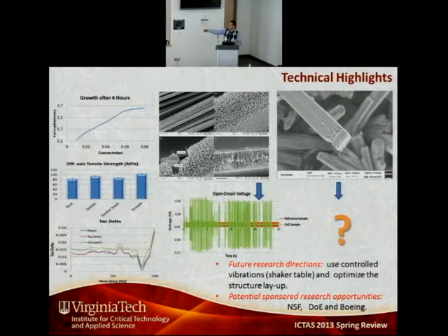So here in the red is the reference sample, where we see that there is no piezoelectric effect or energy harvesting. The green one is the sample with zinc oxide. So we see here that the voltage reached about 0.1 volt. This is an open circuit. So this basically shows us that there is energy harvesting for our device.